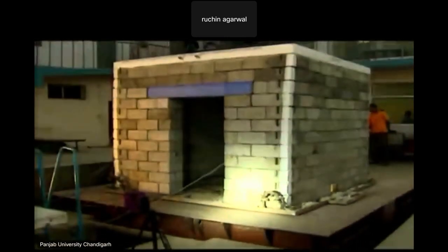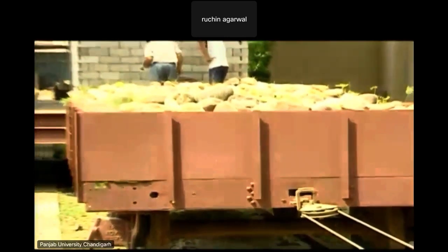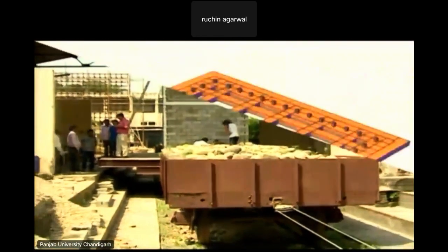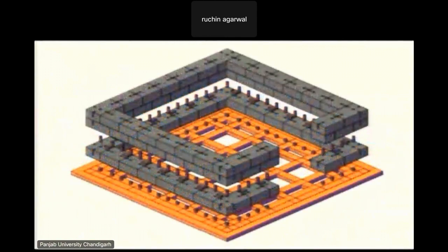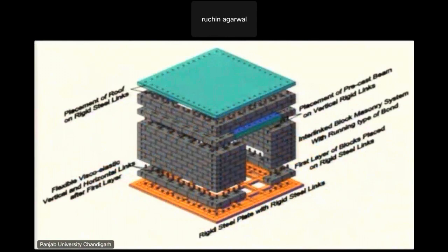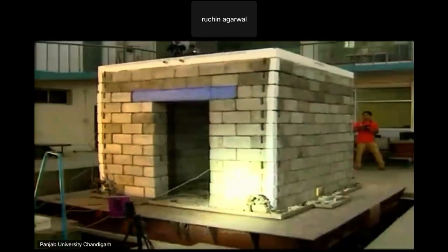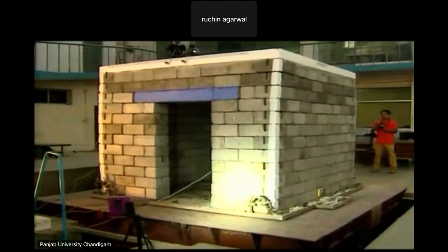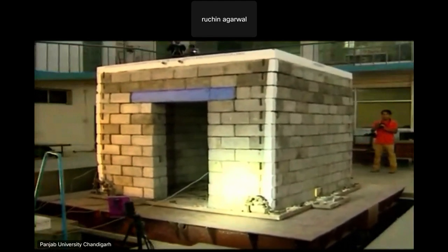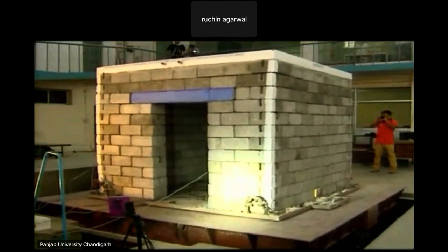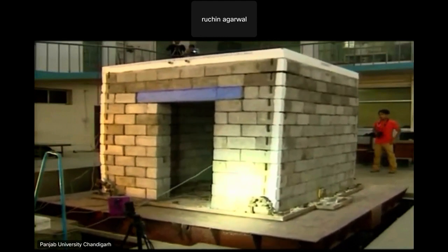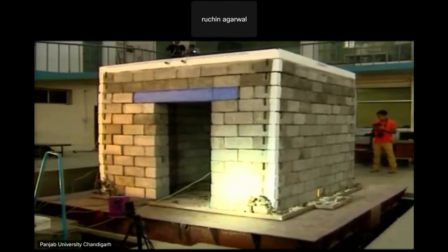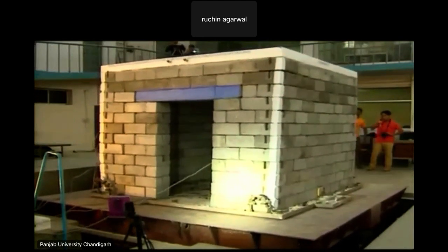The developed technology is tested under severe conditions on shake table and shock table test facilities by simulating artificial earthquake excitations. Its seismic performance is analyzed experimentally. A full-scale housing model with maximum load-carrying capacity is made on the shake table and tested under a series of simulated earthquake motions as per IS code 1893, Part 1, 2002. Peak ground accelerations of 0.18 g and 0.36 g, that is DBE and MCE of zone 5, considering soft soil condition, are applied.